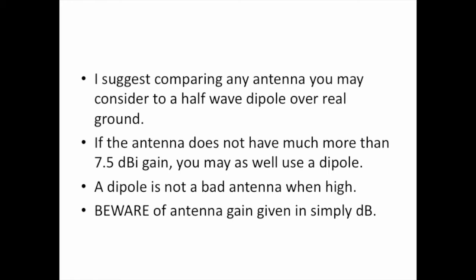Now, I think it's always a good idea to reference antennas to dBi. If you always go back and figure the gain of an antenna in dBi, then you're comparing apples to apples. I could build an antenna and advertise it to have 20 dB of gain. Well, that 20 dB of gain could be in reference to a coat hanger that I'm tuning up with my L-Network antenna tuner.